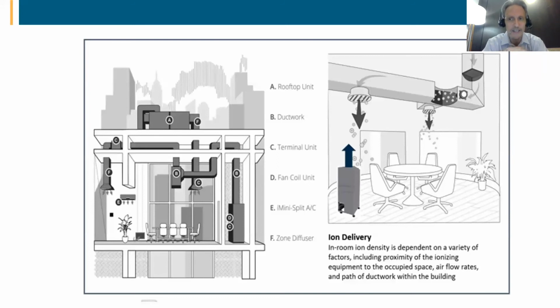On the right-hand side, I show a space. It most certainly could be mounted, as mentioned, and done by ITT in their testing, in a portable HEPA filtration machine directly in the space to ionize the air and immediately agglomerate and bring particles back to the HEPA machine more effectively. They make duct-mounted products that can be mounted in the ductwork itself, closer to the space. And as you work your way back in the HVAC system, as shown on the right-hand side of the slide, it can be mounted in furnaces and fan coils, water source heat pumps, window air conditioning units, PTACs, mini split air conditioning systems, variable refrigerant velocity systems.